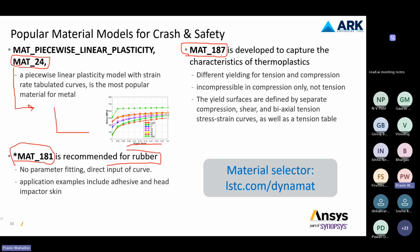So MAT 181 is developed to capture the thermoplastic effects: tension, compression, incompressibility, and compression only or not in tension. So those things for the material are crucial. To carry out this kind of simulation, with this type of material input, you need to use MAT 181, where you can define separate compression, shear, and biaxial tension stress curves, as well as define the tension table. So what type of material is needed for you?